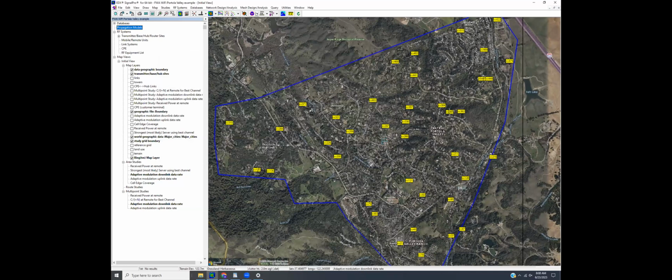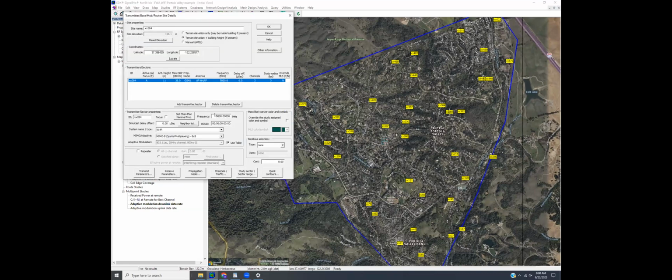And then I define my equipment in the usual way. I can set up my template for what a site's going to look like, set up all the link budget parameters. If you're doing dual band Wi-Fi, if you've got both 2.4 and 5.8 gigahertz, you can just put both of those on as their own sectors on the site. And then, of course, I've selected the system type of Wi-Fi, and I select a MIMO adaptive antenna. In this case, I went with something moderately fancy, an 8x8 MIMO B. We support all kinds of crazy MIMO configurations.